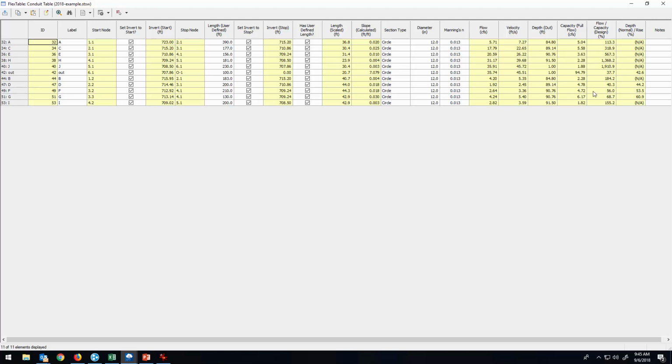So if you look at these percentages, only a handful of pipes are actually adequately sized so far. Anytime it's less than 100%, that tells you it's okay. Actually, it might be oversized. In the case of this 37%, that's saying we're only 37% full. If this so-called 5-year storm that we just put the data in for is our design storm, and we want all of this water to be captured and conveyed by the network, but anything more than that should cause our system to fail, then we actually need to make that conduit a little bit smaller than it is right now.